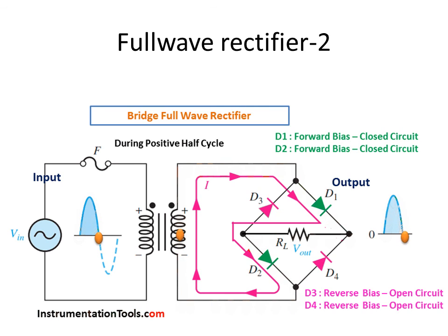And it is not eliminating any half cycles. It will actually rectify. That means all the negative half cycles will be taken to the positive side, so it will maintain all the voltage, unlike in the case of a half wave rectifier.